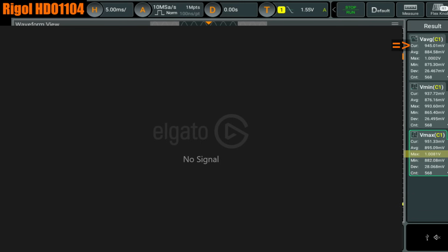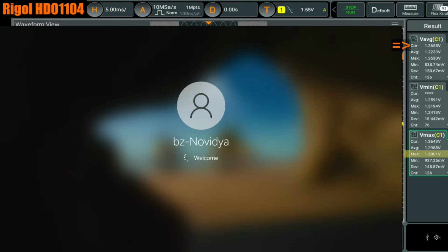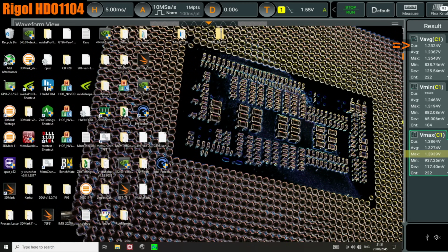negative offset. And this should basically keep us at a maximum voltage of like 1.48, 1.5-ish. Because now every VID request that the CPU will ever make gets lowered by 70 millivolts. And the highest VID requests that my CPU makes are like 1.4 all-core and 1.5 single-core. So those have just gotten knocked way down.